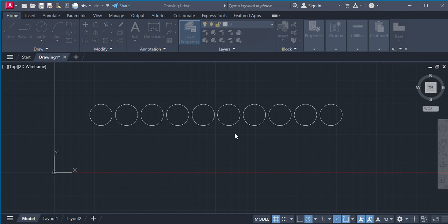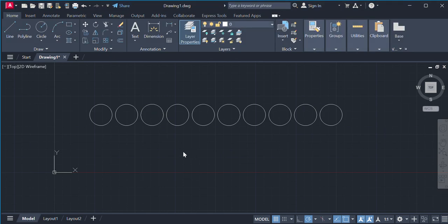Any of these lines should work just fine, but center is the most common one used. You click on it, you say OK. But remember, just because you loaded it does not mean you have selected it. Now you have to select it and say OK. Then we know that our center line has a specific type of line on there.